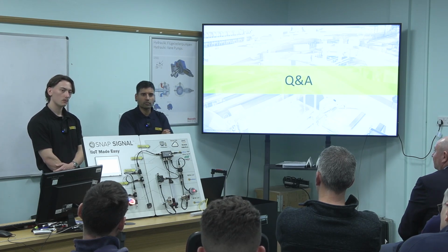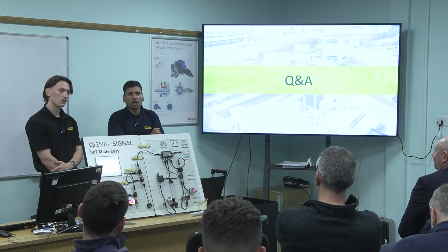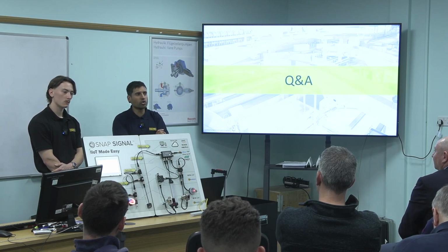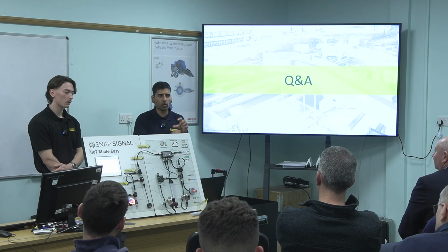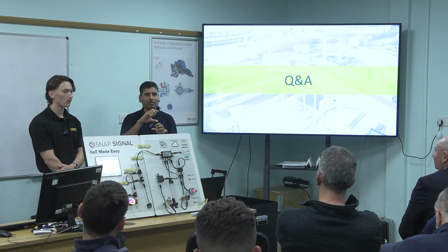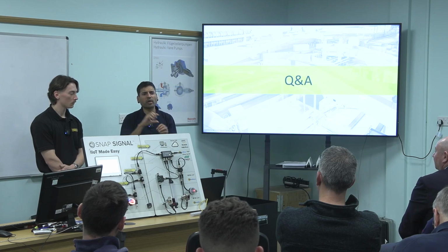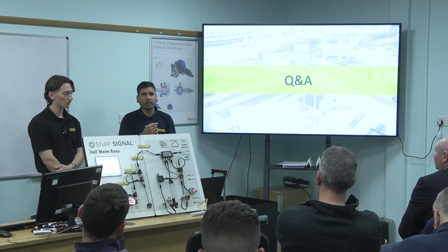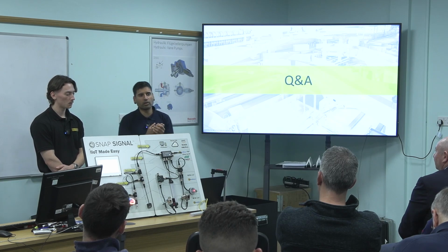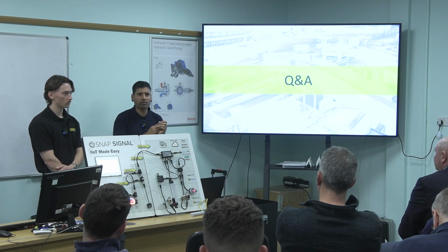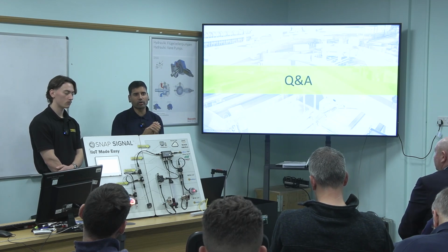Can these be affected by any electrical interference? What, like noise? With our analog converters, we also do inline filters, like chokes, and EMC filters to get rid of harmonics and stuff like that. Being an M12 unshielded, there's less resistance to noise, so that's a good thing with IO-Link.